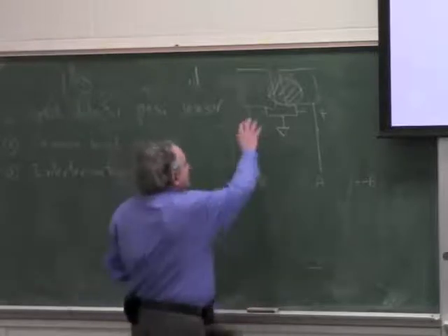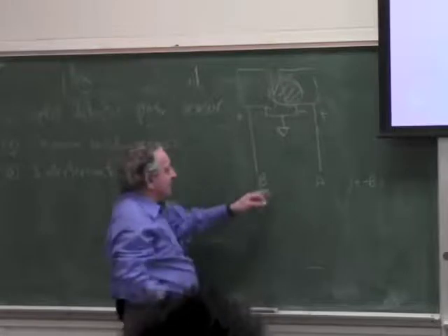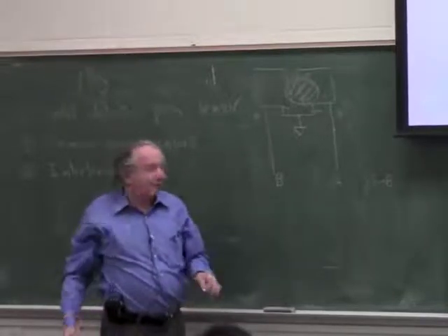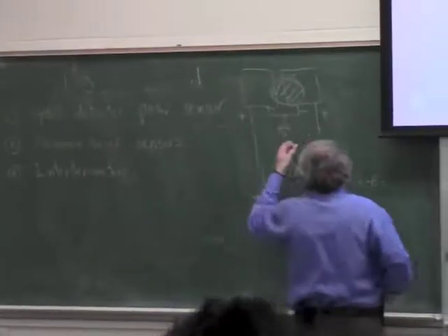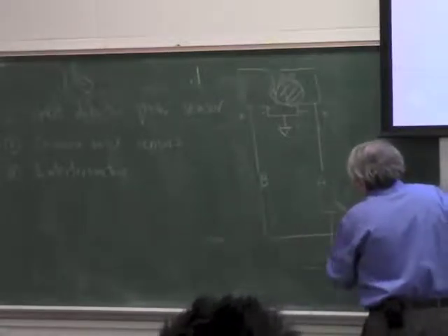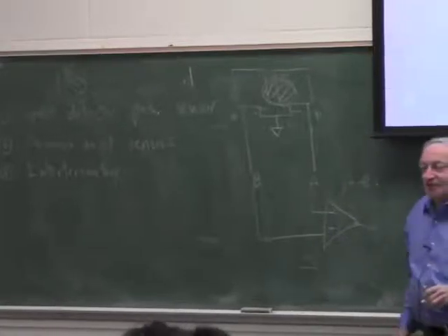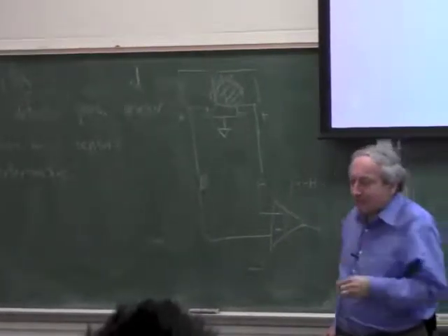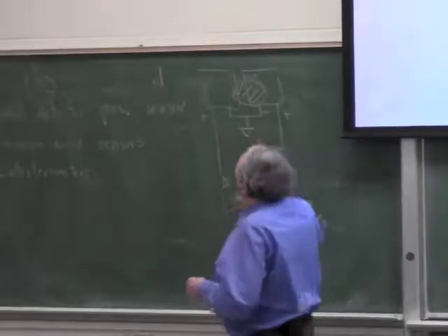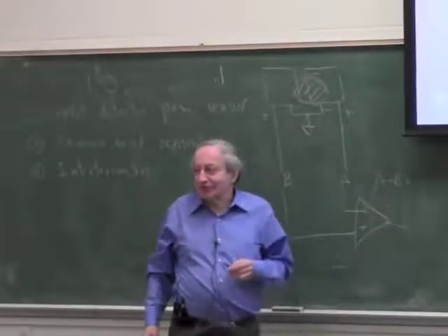Zero. If the light spot is centered, each signal is equal. Now, as the light spot moves to one side or the other, one gets bigger, one gets smaller, just like in LVDT. This is DC, you don't even have AC. You run this into an op-amp, minus plus, and you get the position of the spot. We already learned last week that if I get the position of the spot, I can also get the angle of the spot if I want.